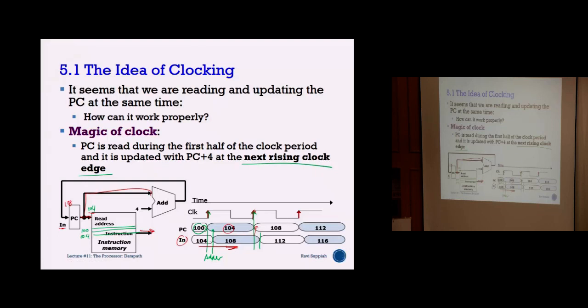The idea is to understand that even though this thing changed, every time we execute, we are actually at the next one. Like we are not at PC, we are at PC plus 4. It's because we reach that counter first while it's still executing. Yes, correct. The adder block is very fast. That's why every time we execute, they straight away go PC plus 4.